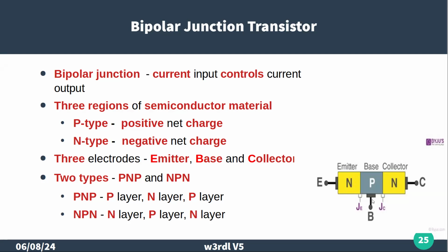That part works like a diode. You can see there it's a PN junction between the base and the emitter. So as you apply a voltage to the base, when you get over the forward voltage drop, because it's the same kind of silicon junction, at 0.7 volts, it will start to conduct through this PN junction like a diode.